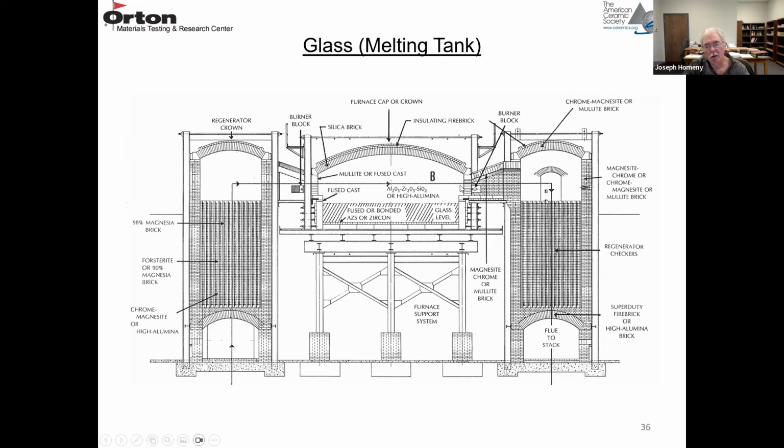So the burners are running here, the hot gases go out here and heat this up. And it's drawing preheated air from this regenerator. So the air goes through here, heats up from this hot regenerator, the fuel is burned, and it exits this way. And then when this is cool, it switches.